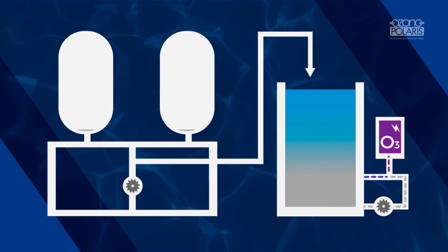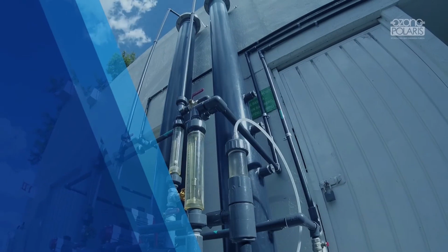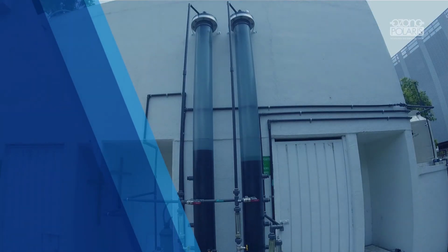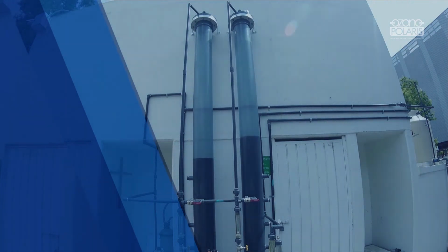Between wash cycles, ozone can be used to oxidize the desorbed contaminants. By washing with ozone once a week and with chemicals once a year, for example, the useful life of the carbon may be as much as 10 times its normal life.